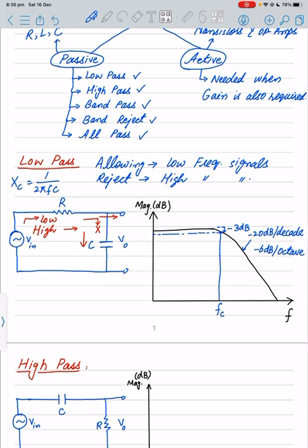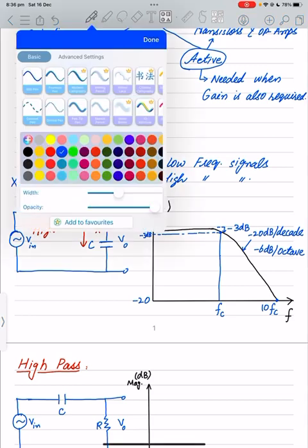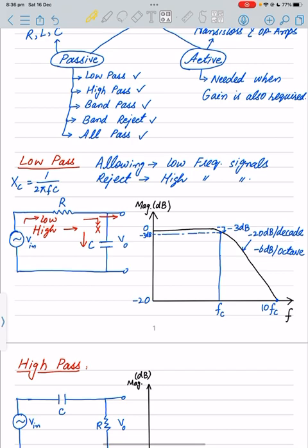And if we say कि let's suppose कि हमारा जो है वो 0 dB से स्टार्ट हुआ था और इस पॉइंट के ऊपर इसकी -3 dB इसके अंदर चेंज आ गया, and then after reaching that point, let us call that -20 dB per decade है, so that will be let's say 10 FC point, so it will be reaching at that point -20. या अगर हम अदर वर्ड्स के अंदर बोलें, so if it's starting with, let's suppose, कि ये 20 से स्टार्ट हुआ था, तो इसका जो कॉर्नर पॉइंट आएगा या कॉर्नर फ्रीक्वेंसी जहाँ पर इसका मैग्नीट्यूड 17 dB हो जाएगा, that will be that point, और फिर वो करते करते यहाँ पर पहुँचते पहुँचते that will be the 0. So this all depends upon the range of the horizontal and the vertical axis.